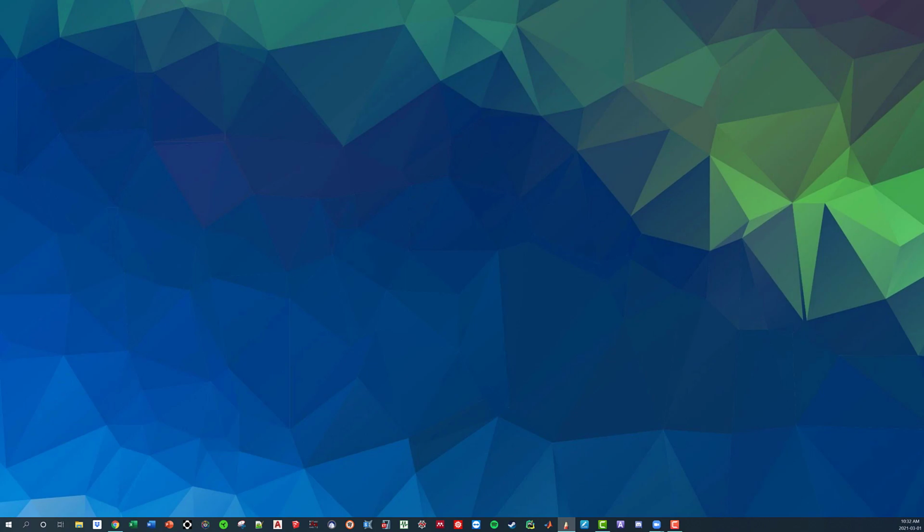So what happens is to get to this point right here, everything is based on this configuration right here. Then once we get to this point, this becomes the new reference configuration, and we try and get to this point over here, and then so on. So then this becomes the new reference configuration, and then we go to this point here. So does that make sense on how ABAQUS starts to account for these geometric nonlinearities? Besides buckling, we'll talk about that a little bit later. But does that make a little bit more sense to you guys on what's going on?